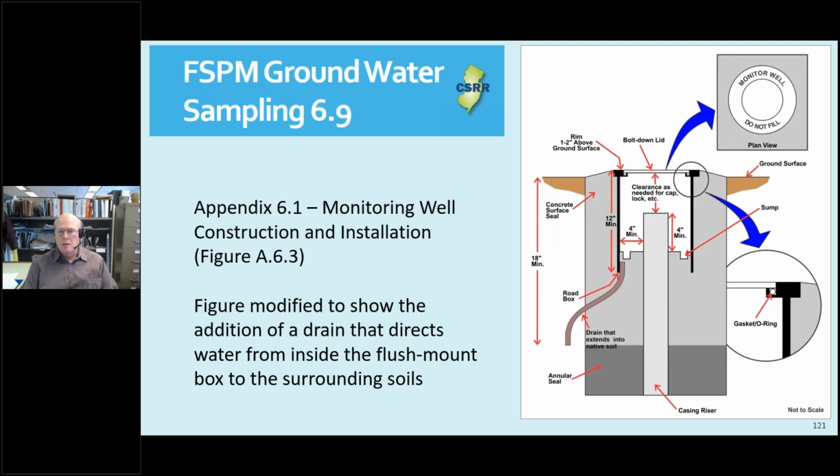It is recommended that this information be with the sampler during the sampling event and included in tables of well construction information. Since the volume average sampling method produces a sample that represents a larger zone of the aquifer, it is recommended that the volume average sampling method be used for initial and closeout sampling events.